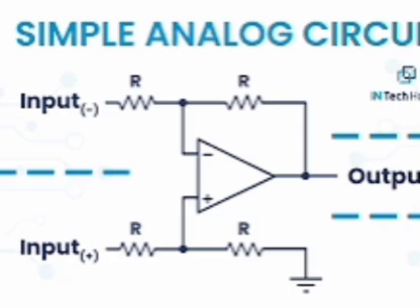Input impedance of common collector amplifier is highest among CE, CB and CC. Output impedance of common collector is lowest among CE, CB and CC. Darlington pair is known as a super beta circuit. It is used where very high input impedance and high current gain are required. Voltage gain of CB is highest and current gain of CC is highest. CE has highest power gain.